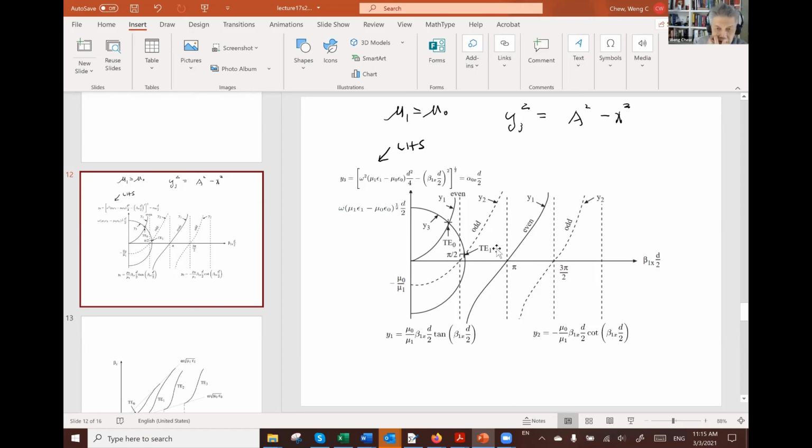Whereas for the TE1 mode, if you make the radius smaller than a certain value, then you wouldn't get a solution where alpha 0x is a positive number. You actually want a solution where alpha 0x is a positive number so that the wave is evanescent. So if you find a solution where alpha 0x becomes negative, that's a no-no. That is a solution where you don't have an evanescent wave outside the dielectric slab and the mode is not guided. Okay, so are there any questions on this?